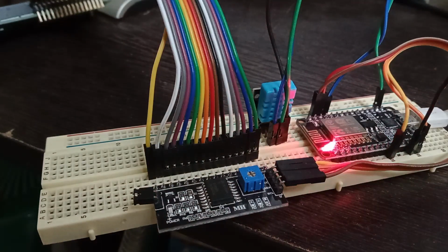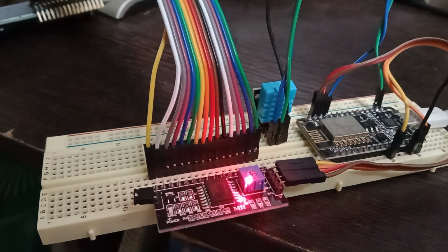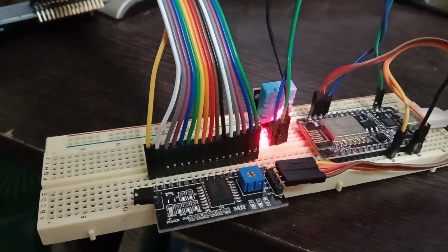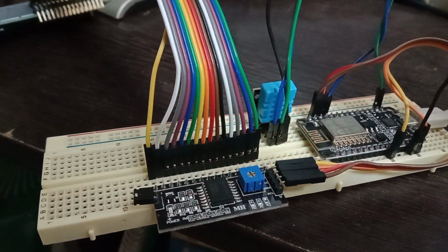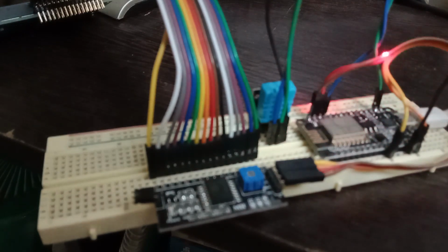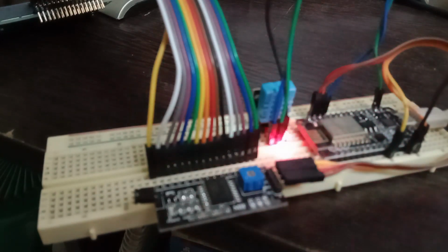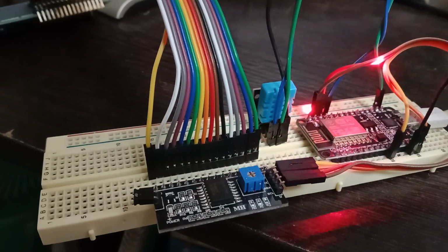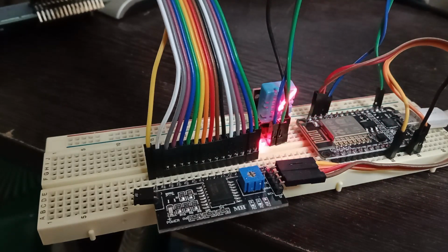If you see, this is the NodeMCU board, and we have talked about the PCF8574 connectivity, right? This is the I2C connectivity, and you can see the I2C pins connected here. And this is the DHT11 humidity sensor, powered from 3.3 volts from here. You can see the green wire coming out, and then the black wire is ground, and it is connected to D3, which is the blue wire coming from the DHT11 to the NodeMCU.